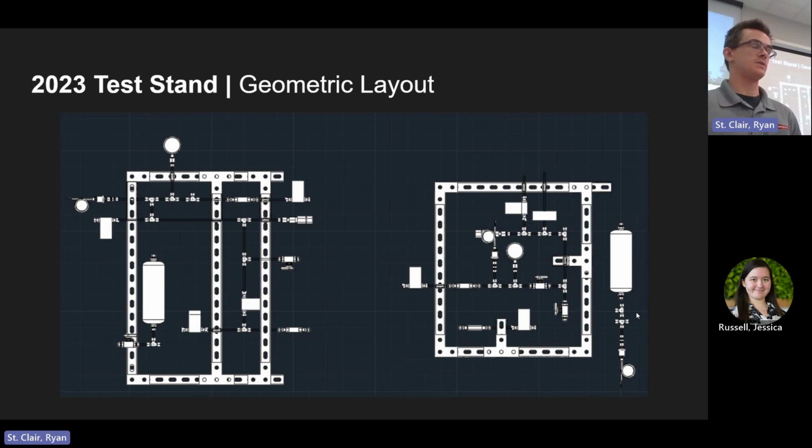That's part of that filling procedure process. So we have that thermocouple here, and then pressure, or the nitrous oxide when we're actually firing, would go across the flex line here into this solenoid valve, across this check valve, and then go into the rocket engine again. So that's kind of our geometric layout.